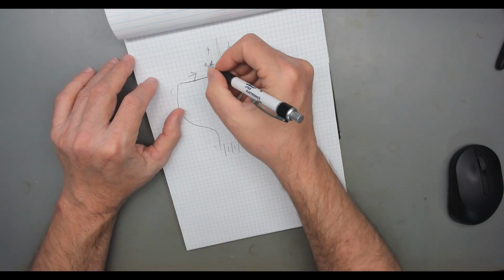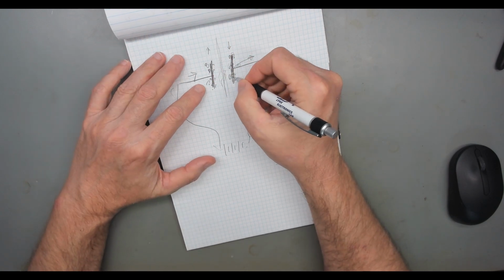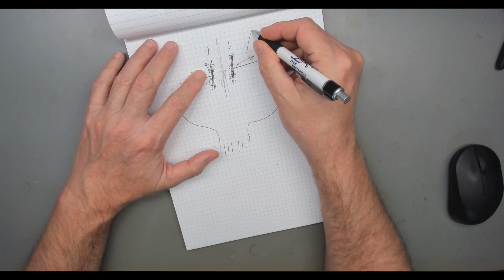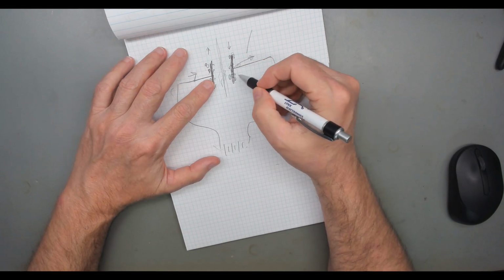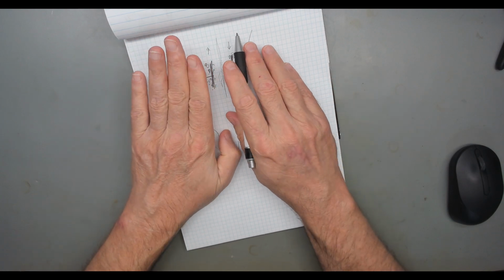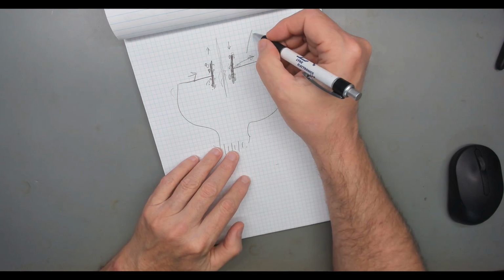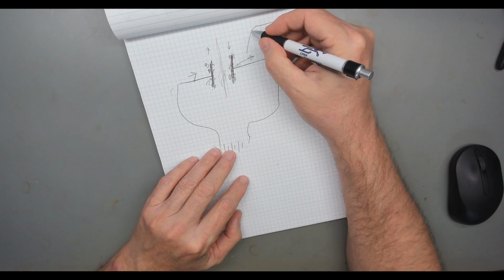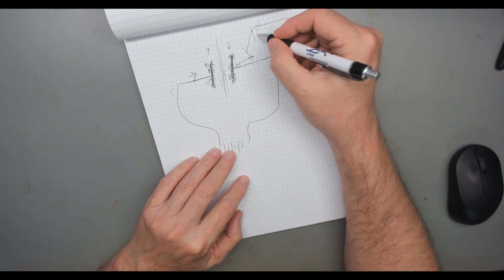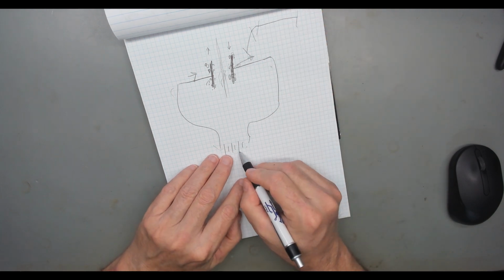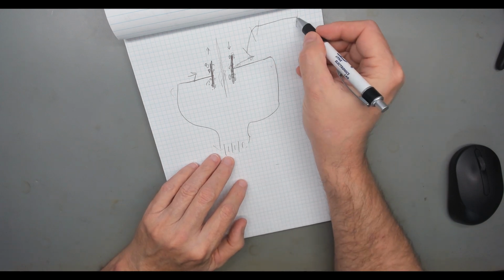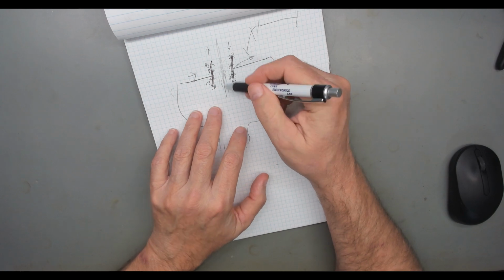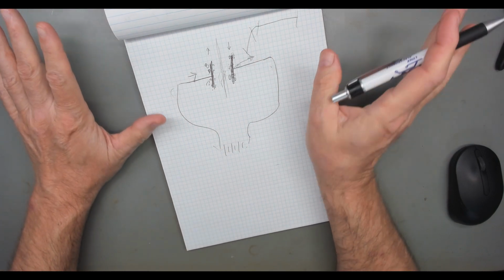Now, as this happens, as you build more electrons on one side and less on the other, you create a voltage in this capacitor. So the voltage climbs. And at some point, when these plates are at the same voltage as the supply, it will flatten out and be that voltage. There is current moving during this point. There will be no current from the point when it matches the battery voltage until forever. It will sit there, other than we're going to discount and remove any leakage in the capacitor. Let's imagine it's a perfect capacitor.